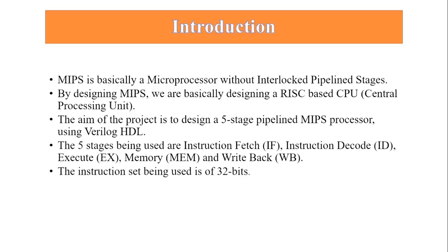Basically, MIPS is a microprocessor without interlocked pipeline stages. By designing MIPS, we are basically also designing a RISC-based CPU. MIPS includes 5 pipeline stages, which are instruction fetch, instruction decode, execute, memory, and write back stages. The instruction set being used here is 32-bit.